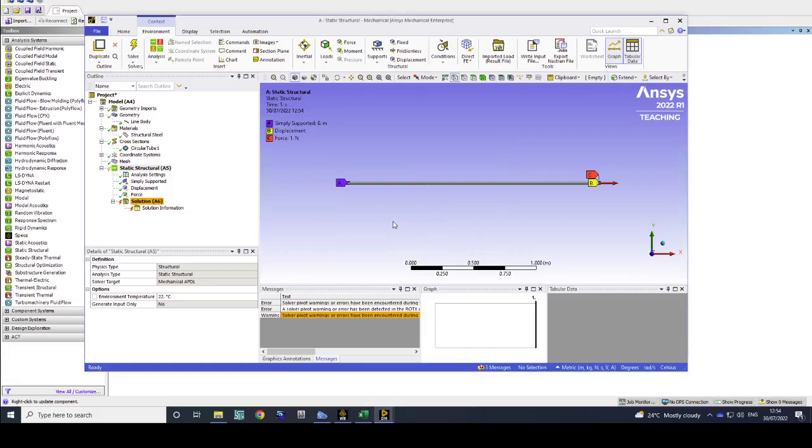So you may wonder what degree of freedom is now open here. If you remember the beam elements, they could have bending, but they could also have torsion, which means rotation about their own axis. We have not fixed that rotation. So essentially it means that if we set this beam in rotation about its own axis, there is nothing to resist it. Therefore, that degree of freedom is completely free, and that's what leads to the singularity of the stiffness matrix.